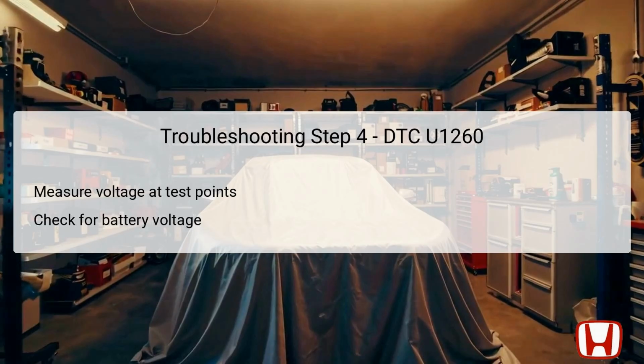Ensure the vehicle is once again in the on mode, while the auxiliary transmission fluid pump's 4P connector remains disconnected. Measure the voltage between test points of the auxiliary transmission fluid pump's connector terminals while connecting them to body ground. If battery voltage is present between the terminals, it indicates that the EOPSTS line is functioning correctly. Finding no voltage leads you to investigate further into the EOPSTS line, as it represents critical electrical feedback essential for the auxiliary pump's correct operation for transmission fluid pressure management.